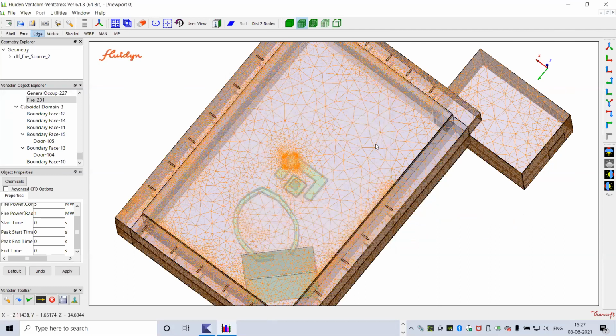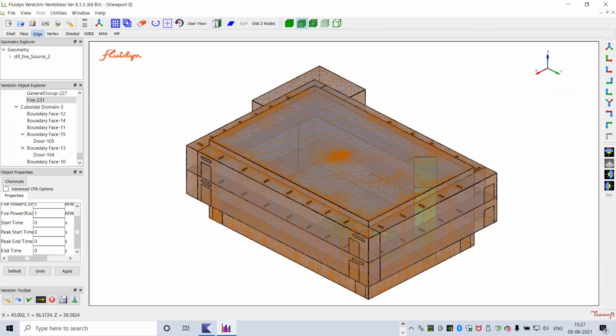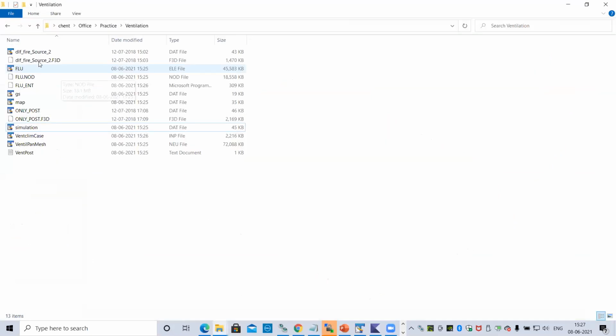Once these case files are dumped, I will tell you how. This was the base geometry file. This is the simulation data which will be used later for reloading the setup. Apart from that, we can see the fluid element information, nodal information, and group information. These are the INP files. These are the basic inputs which the solver will read, and it will generate some supportive files later. So no need to worry about that.